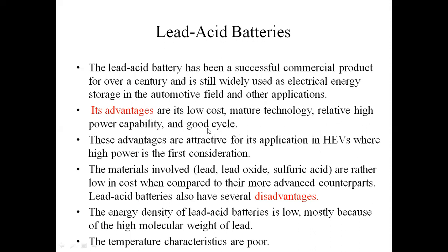Good life cycle means the battery charging time is very short, and its charging and discharging lifetime is very long. That is a good cycle. Next, the cost is very low, with mature technology and relatively high power capacity. These lead acid batteries operate at high capacity. The advantages are attractive for hybrid electrical vehicles, where high power is the first consideration. When we are designing electrical vehicles that require high power, mostly lead acid batteries are used.